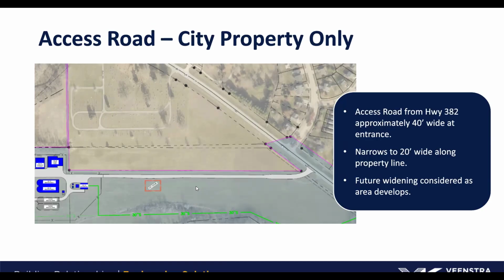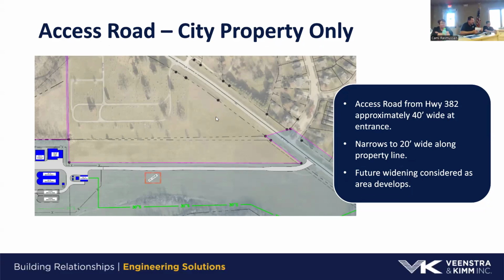Just out of curiosity, our standard street width now, 29 is pretty common. 29 to 31 is generally what we're looking at for anything that has significant traffic. We can go down. I think there's maybe some 26 footers coming out there that we've allowed. Those are more residential, low volume, but usually we're looking at 29 to 31.